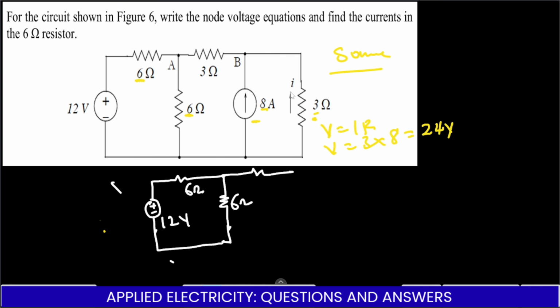So we have these two resistors here, and they are in series, so we can add them together. Let me redraw the two together here. So we get 3 ohms here, another 3 ohms here, and the voltage that we have transformed, which is 24 volts. Very good. So this is our resulting circuit.